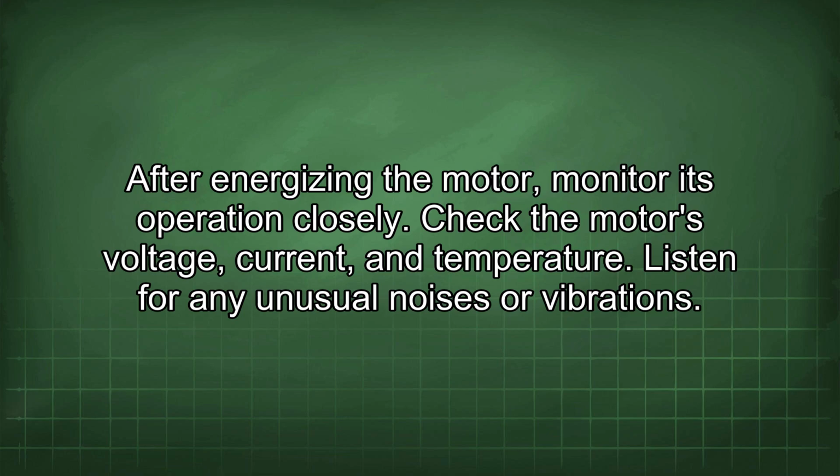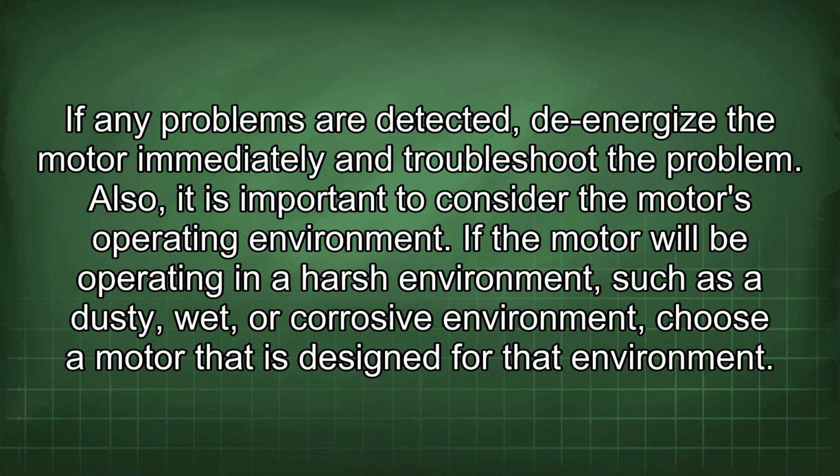After energizing the motor, monitor its operation closely. Check the motor's voltage, current, and temperature. Listen for any unusual noises or vibrations. If any problems are detected, de-energize the motor immediately and troubleshoot the problem.